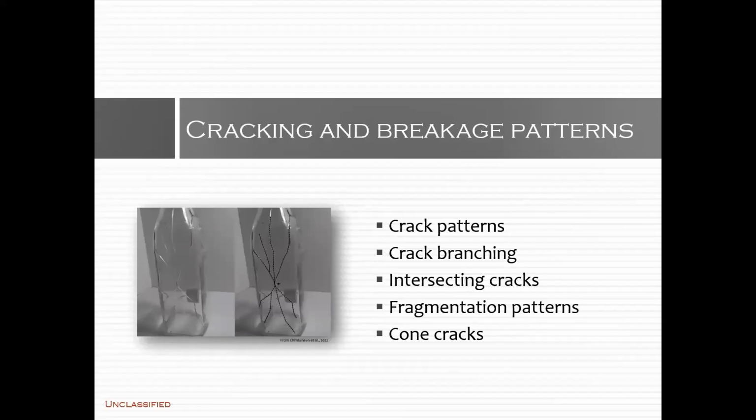As the crack propagates, minor deviations in the direction of local principal tension modify the plane and direction of cracking. And if stresses are too great to be dissipated through a single crack, multiple cracks might be created. Fracture paths aren't random, but they reflect deviations and the need to dissipate stress. They can also provide information about the fracture origin and energy.